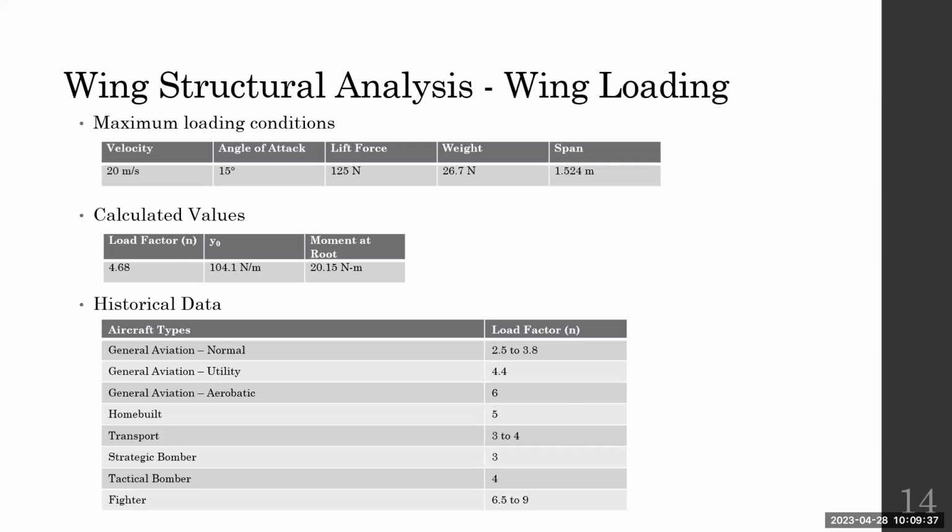Okay. In reality, that's probably not the case. So a couple of recommendations is, one, look at the landing scenario, because that's actually a maximum loading condition. I think Tom, the Northrop guy, grilled us on that before because we didn't consider it. And also consider your actual attachment points of the wing, because that's going to be what's reacting a lot of the load. Okay, thank you.